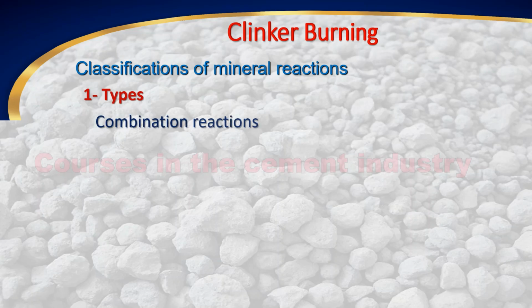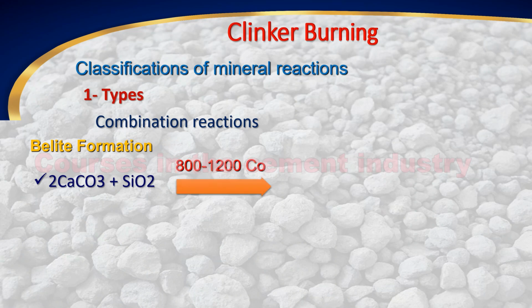Classifications of mineral reactions. Types. Combination reactions. 1. Belite formation. 2CaCO3 plus SiO2 at 800 to 1200 degrees. Result: C2S plus CO2. 2. Alite formation.